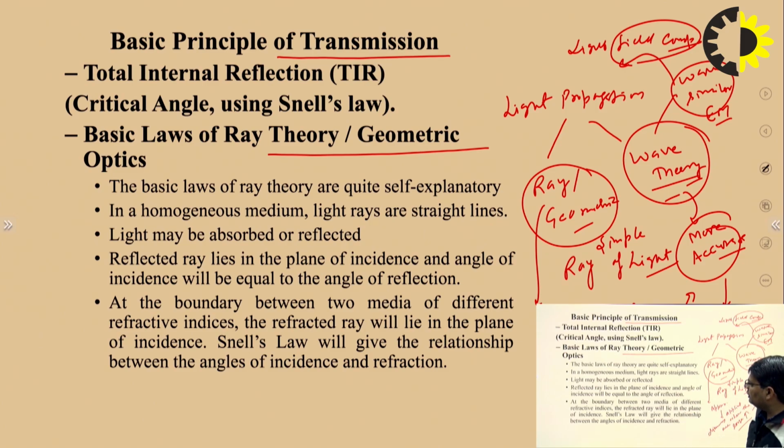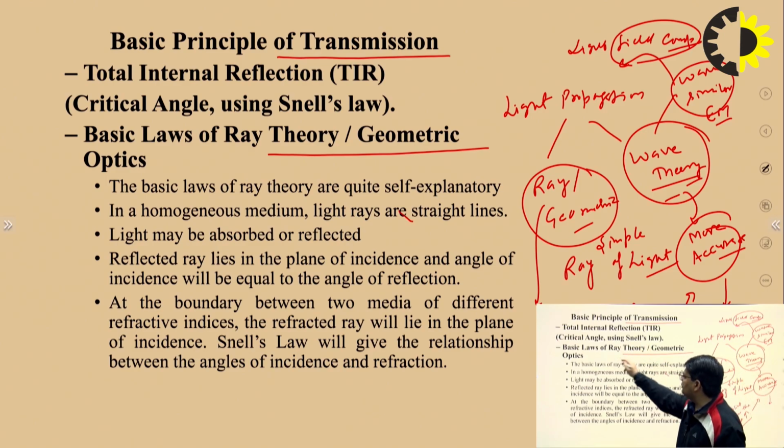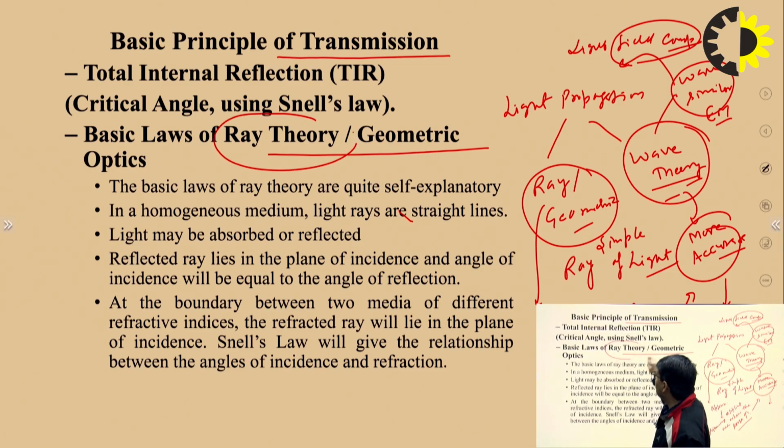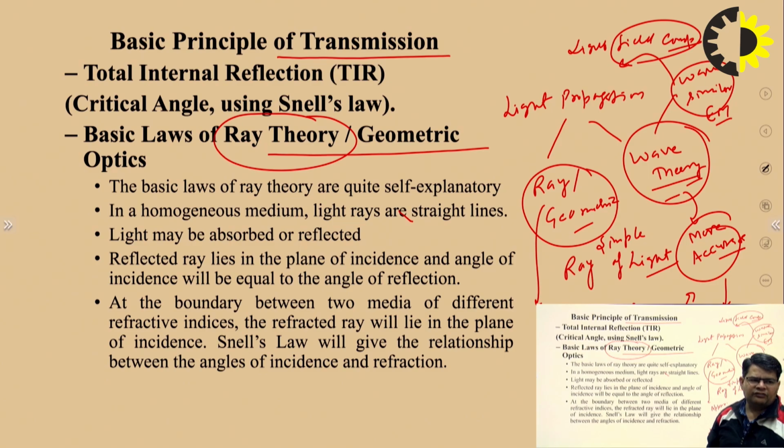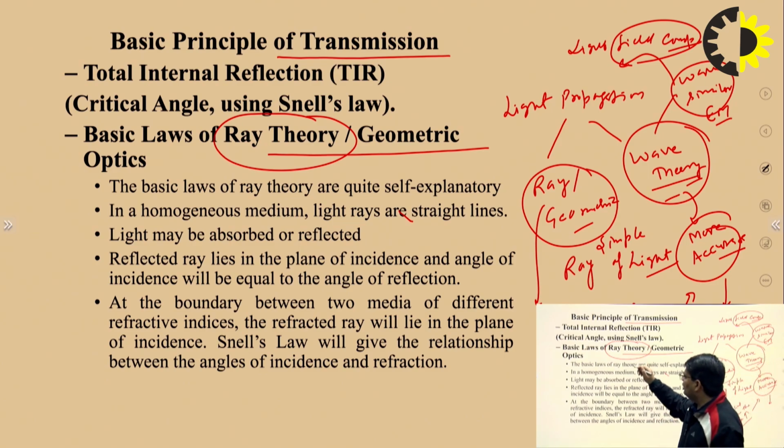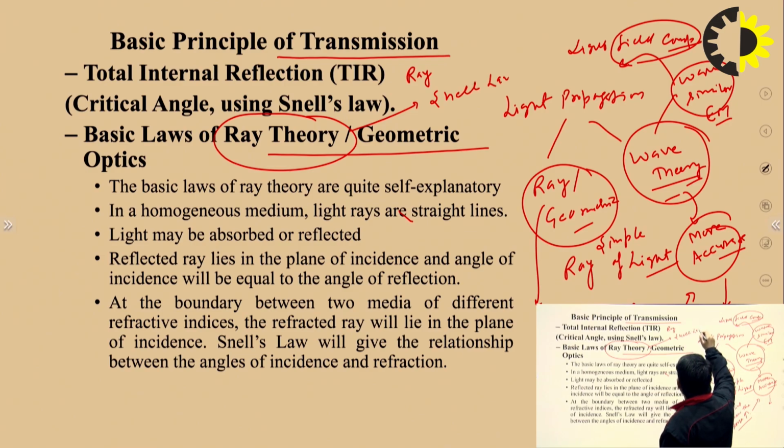So first of all, in this lecture we are going to cover the ray theory concept. We are applying the ray theory concept to explain the propagation of light inside the optical fiber cable. To explain this ray theory or ray geometrics, we will consider a few points. Light is considered as a simple ray. We will apply the rules of geometric optics, such as Snell's law.